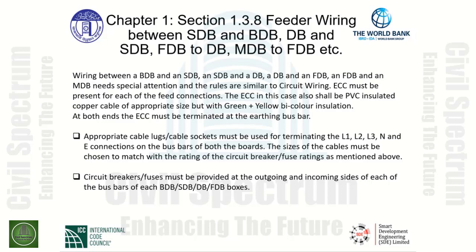Earth continuity conductor, or ECC, must be present for each of the feed connections. The ECC in this case also shall be PVC insulated copper cable of appropriate size, but with green plus yellow bicolor insulation. At both ends, the ECC must be terminated at the earthing bus bar.